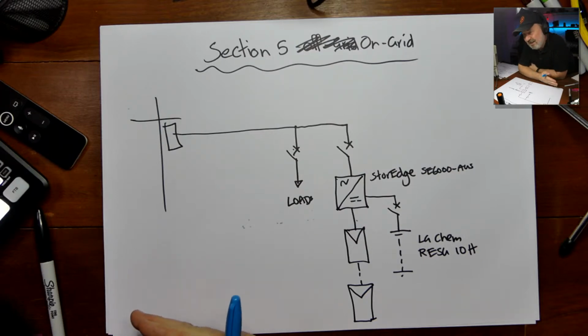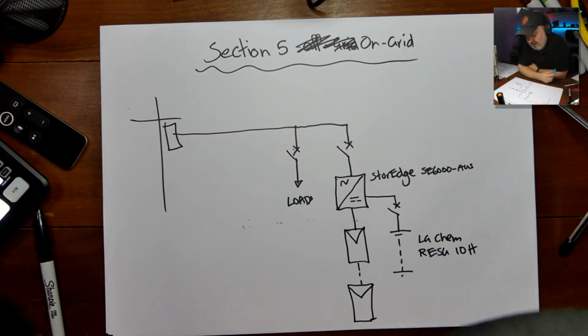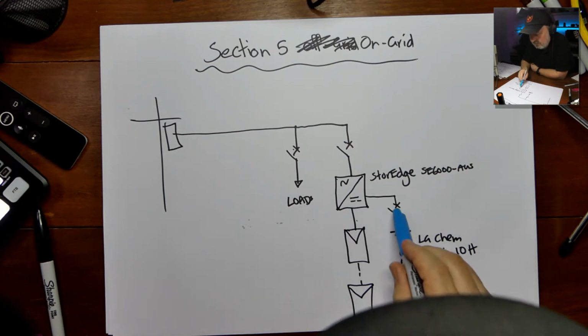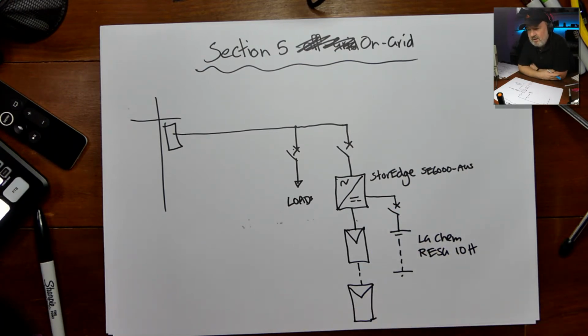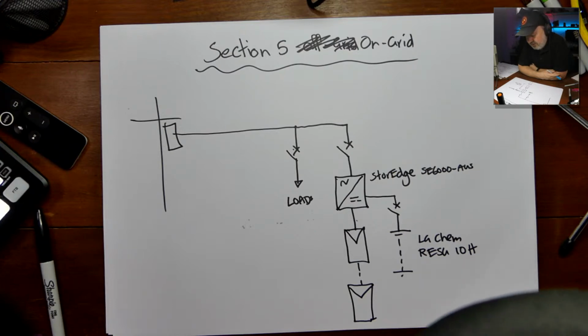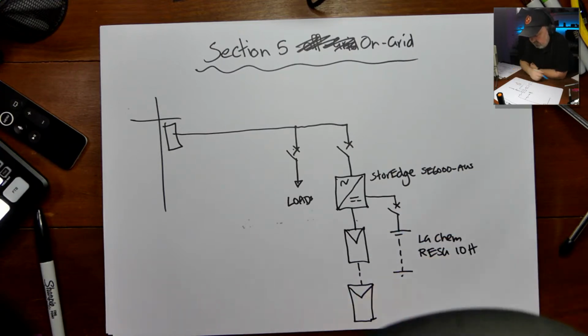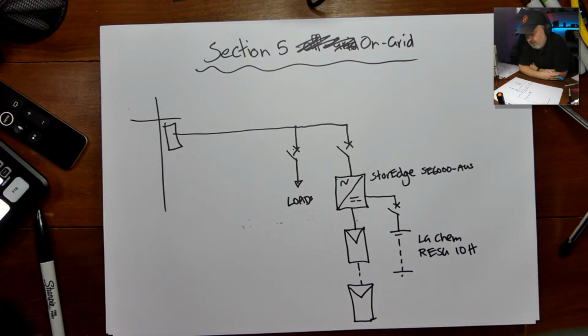It's got a double action latch. You've got to do a lift and pull in the right order to open that little hatch to get to the circuit breaker. So it is technically readily accessible, but if you think about the intent, it's that if something's going wrong, someone can quickly turn it off and they don't have to read a manual on how to open the door. So in practice, most people are putting an external isolation point external to the battery unit. But if you can convince your inspector that you've trained the customer and they can actually open that door in a hurry, maybe it's okay.